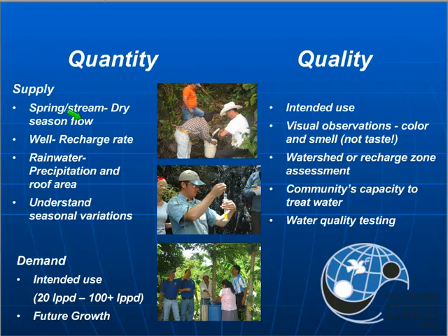And so understanding what that situation is in the dry season is essential for doing the capacity side of your supply-demand analysis of a spring or a stream. For a well, this can be a big mystery until you do some drilling, but sometimes you can visit nearby wells or talk to drillers in the area who have some experience to get some sort of estimate before you even drill that well at your particular site, to get some idea of how much you can pump.